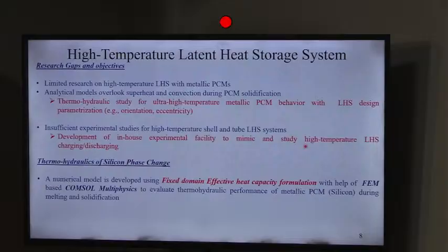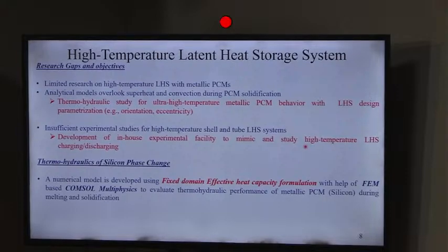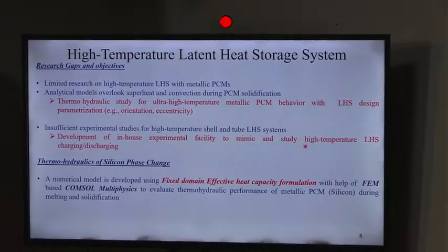That energy you can get, say, from solar, where you have a concentrated system like a parabolic dish collector with the energy focused at its focal point, and then you take it and utilize it for melting the sand. You can also take it from waste heat. Suppose you have a metallurgical operation in an iron and steel plant; there also the metallurgical operation takes place at a very high temperature, say 1200 to 1500 degrees centigrade. So whatever waste heat is generated in that metallurgical process of iron and steel can also be taken, recovered and utilized for melting the sand.